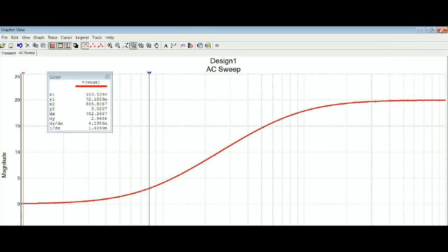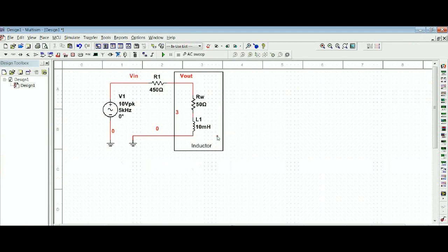So I'm going to eliminate this, and analyzing this at high frequencies, well, the X sub L equals 2 pi FL, and as F goes to infinity, the inductive reactance here also goes to infinity, which basically means this part is not in the circuit. In other words, V out equals V in at super high frequencies.